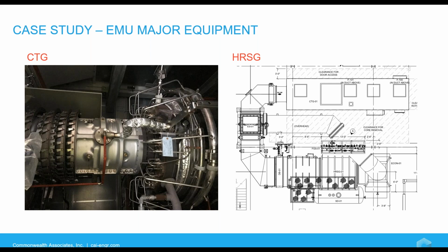The new HRSG was significantly larger and ended up replacing one of the old boilers while the other two boilers supplied steam during the summer. And then you can also see the exhaust stack shown here, which is that bold square there on the left side of the right picture. It also has a bypass to allow operation of the CTG if steam production is not required or if it's being provided by the boilers.